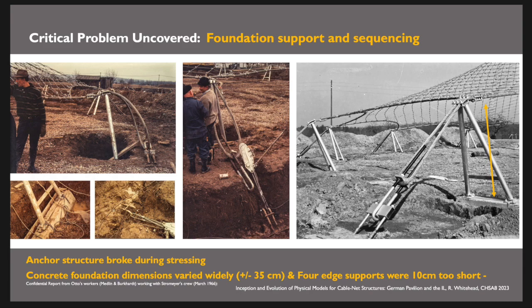There were some problems that came up, so it's a really good idea that they did this. One of the foundations, as they were pulling this thing together and tensioning it, actually broke. You can see here how that is now loose, how it popped out from here. They did this right before one of their major demonstrations, and so they found out that there was a sequencing issue with that. The connections were a little bit difficult with it.